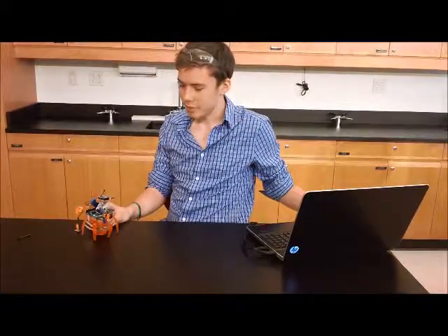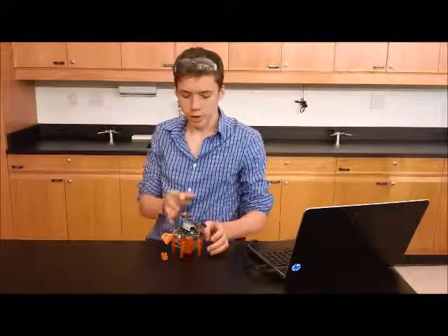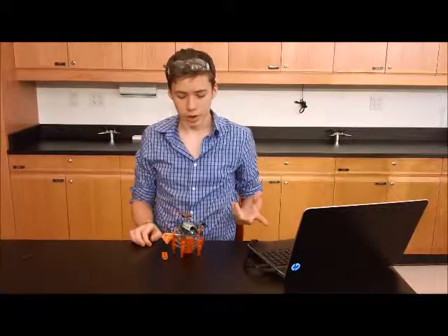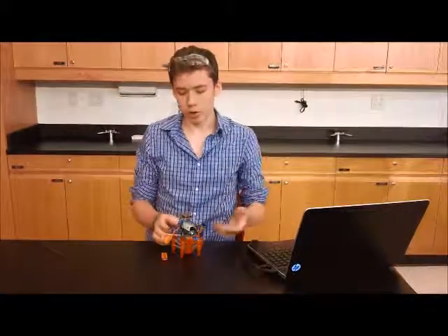One of the main issues that I have faced along the way has been my worst enemy, static friction. I've tried to combat it in a number of ways. At first I could only give the motor 5 volts directly, so what I ended up doing is hooking up the motor directly to the 9-volt battery and then putting transistors after the load so that I could control the voltage going to it, which has worked fairly well because it's given me more control of range.